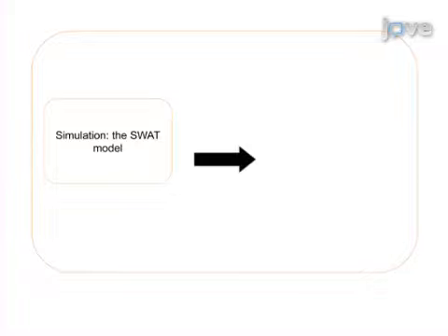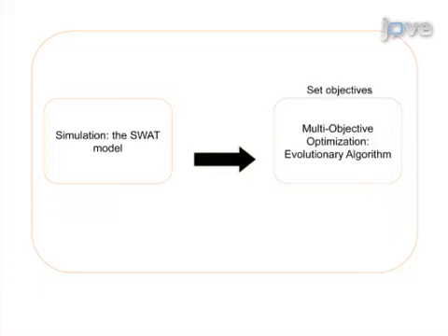To achieve the optimization goal, first select a calibrated and validated watershed process model and model representations of conservation practices. As a second step, the environmental objectives to be maximized are selected, and costs of conservation practices are obtained, which allow for the evolutionary algorithm component looking to simultaneously optimize along environmental and cost objectives to be invoked.